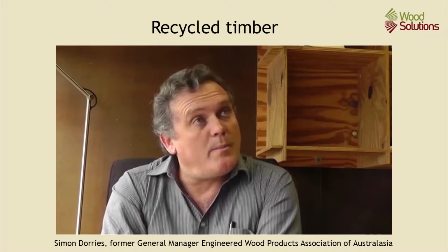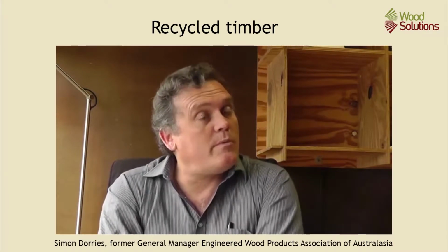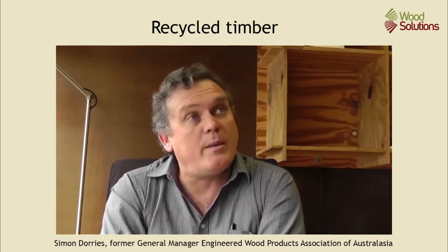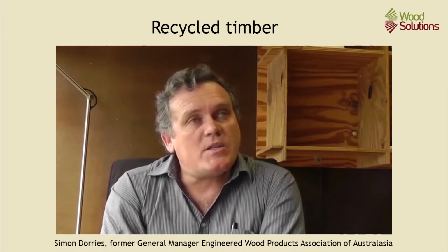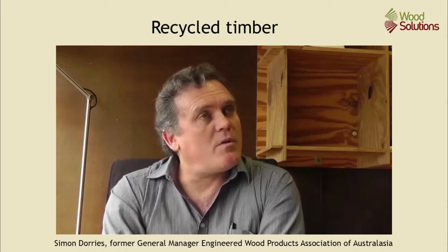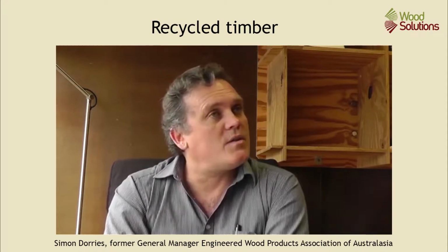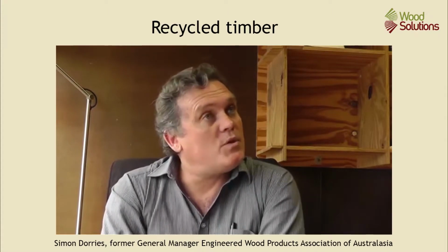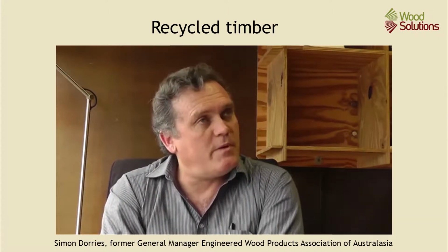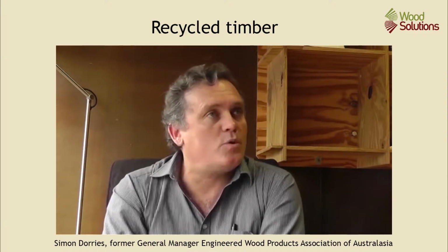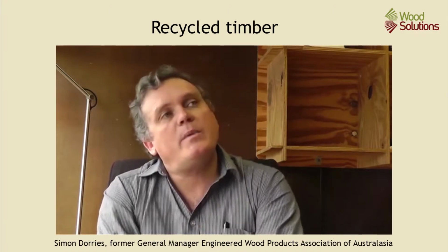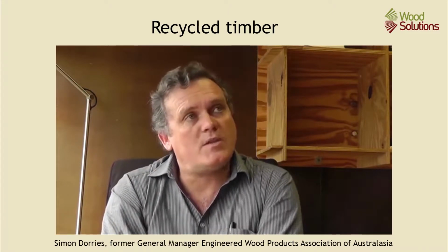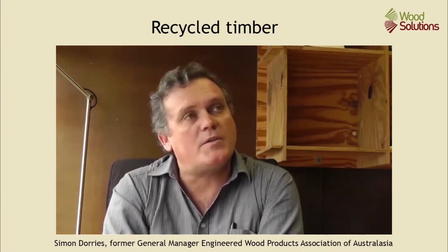So if you want a plywood product to be painted and you want it to perform particularly well, you order or you specify a quality B grade veneer. A C grade is a non-appearance grade, so it allows knots, it allows holes, it allows defects, it allows putty splits, but the surface must be filled and sanded. So for example, knot holes will be puttied and they'll be sanded, and a D grade is a non-appearance grade with open defects, so unfilled splits, unfilled holes.